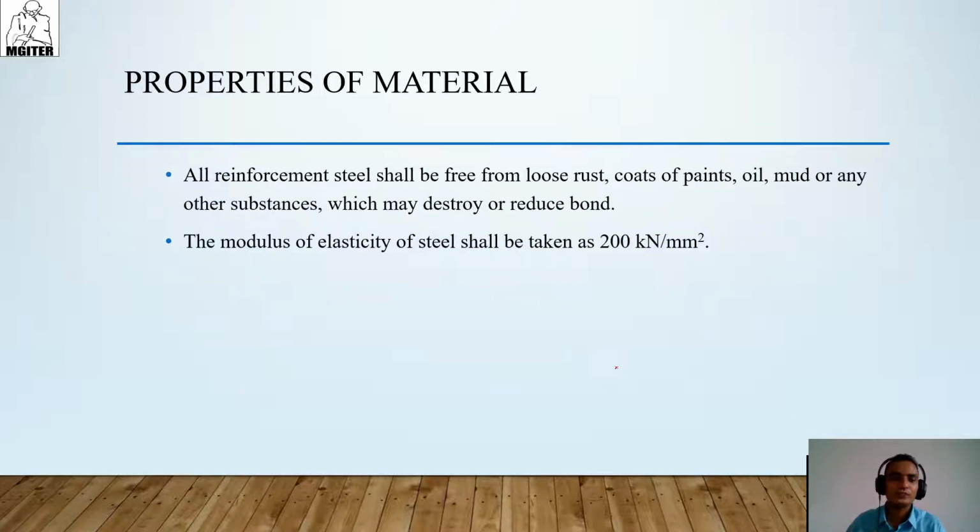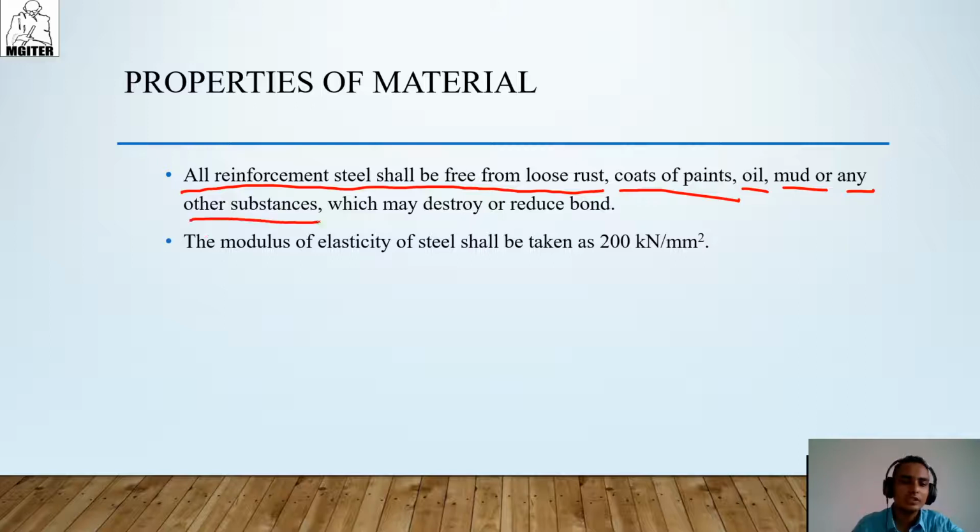Okay. Then after this are some precautions. All reinforcement steel shall be free from loose rust, coat of paints, oil, mud or any other substances which may destroy or reduce bond.